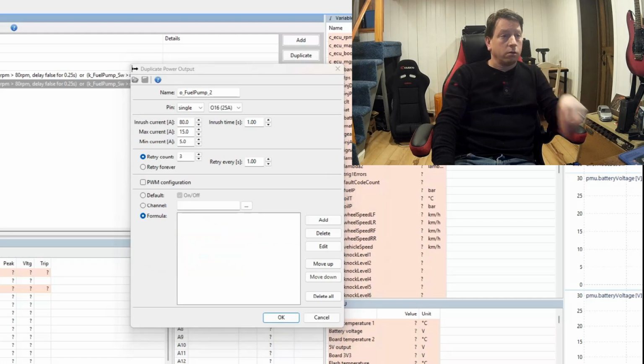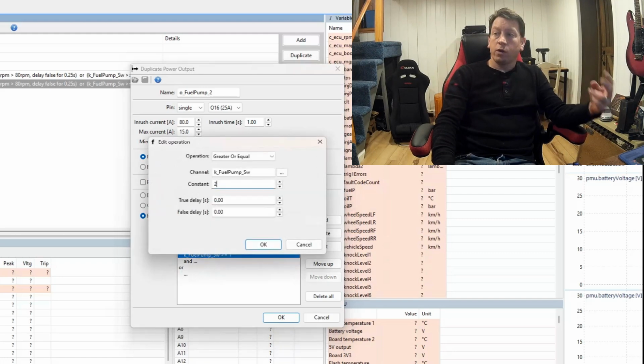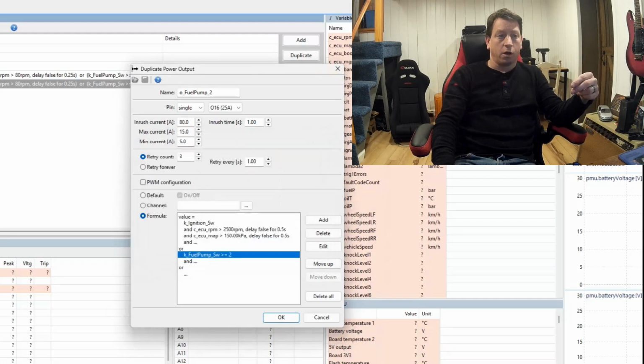The other thing we're going to do is move the fuel pump. So only when you press the button twice is the second pump going to turn on. In this case, we're staging the pumps, and you can make them work either way, where the switch either turns on only one pump or slowly turns all your pumps on. In this case, when you press it once, it's going to turn on lift pump and pump 1. When you press it twice, it's going to leave those two pumps on and now also turn on pump 2.